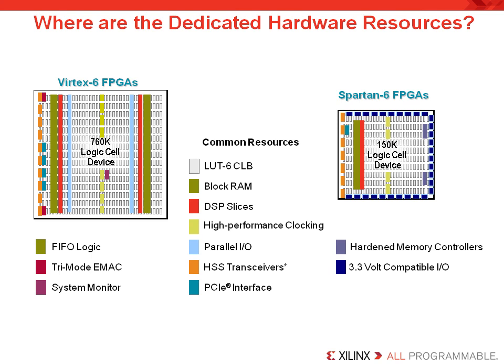In Spartan-6 FPGA, the high-speed serial transceivers are located on the left edge. This is only available in the LXT subfamily. The LX subfamily has regular I/O on the left edge of the die. Note that in the Virtex-6 FPGA, CLB logic is placed with the block RAM resources.